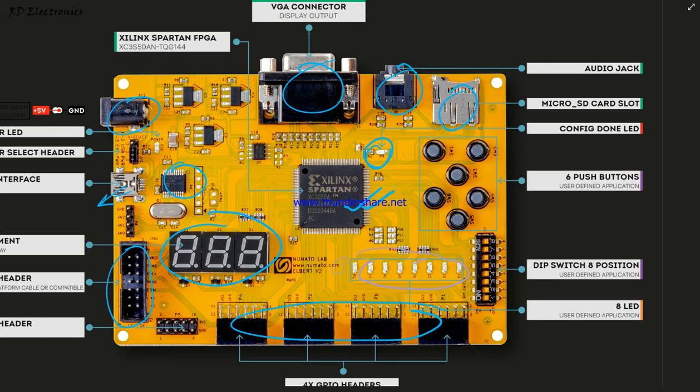FPGA is faster than CPLD devices, and in terms of architecture, FPGA is considered a fine-grained device, while CPLD is coarse-grained. FPGA is a RAM-based digital logic chip, while CPLD is EEPROM-based. EEPROM means electrically erasable programmable read-only memory technology, and FPGA's RAM means random access memory technology. So why is FPGA more popular? Because FPGA is capable of more complex technology and architecture than CPLD, and it is more secure to store the design within the built-in non-volatile memory, and FPGA has 1000 times more resources. These are the basic advantages of FPGA over CPLD.